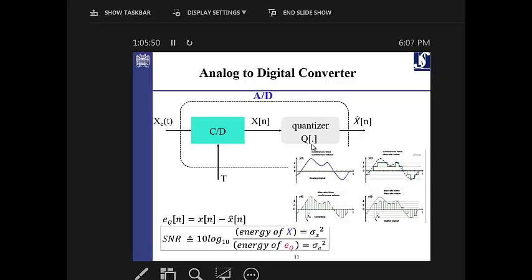The American standard is mu-law, and the European version is A-law. That exponentially compresses the signal. It means that it will assign fewer bits to the higher levels and more bits to the lower levels. With this kind of quantization, the signal passes through the A to D converter, and then you can deal with it as a byte or word, depending on the A to D converter level. We will explain that a little later.